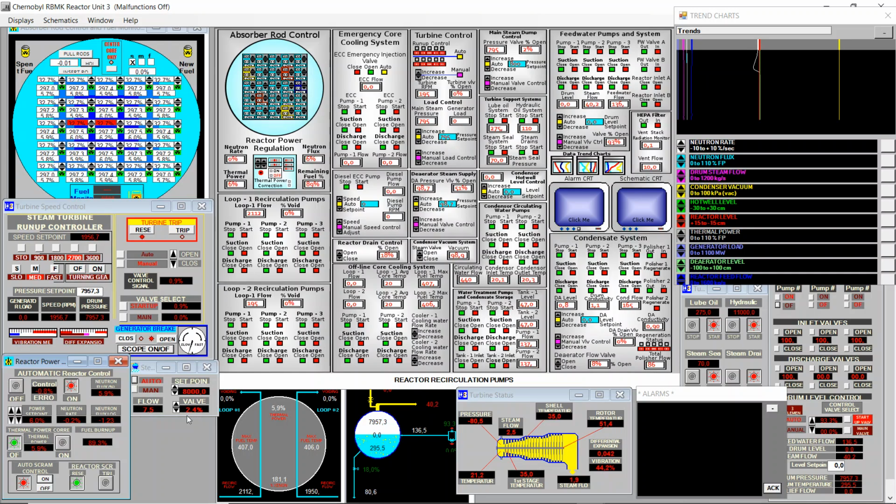And even if it goes to 0, I will not worry too much, because the turbine is at a very low speed already. Well, not very low, but like at half of the spin down. The valve is almost at 0% of opening and we don't get vibration, so we could already close totally the valve. I think we don't need pressure in the drum anymore.